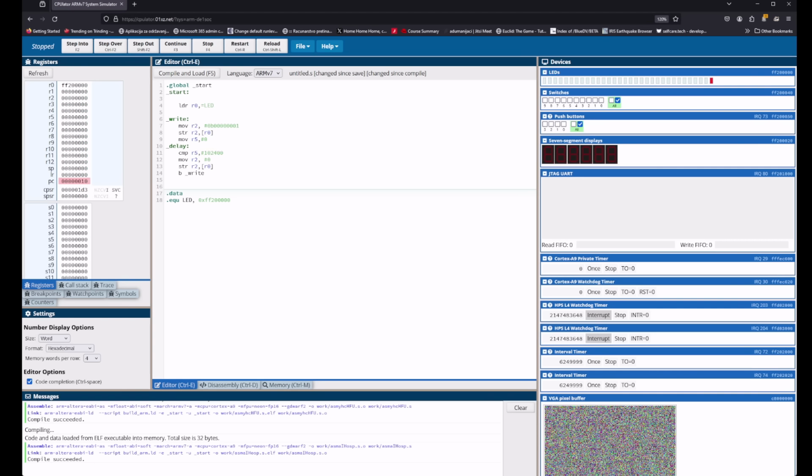let's use this number. This number is something that is going to work because it is able to store this number in the space selected for the instruction. So I'm going to compare this R5 to this number, and then I'm going to say now if this thing is not equal, I'm going to be jumping to underscore delay. If they are equal, this is not going to happen, so this is not going to go then. What I also need to do, I need to add 1 before I compare, because I need to increase the value that I have by 1. So this should be it.